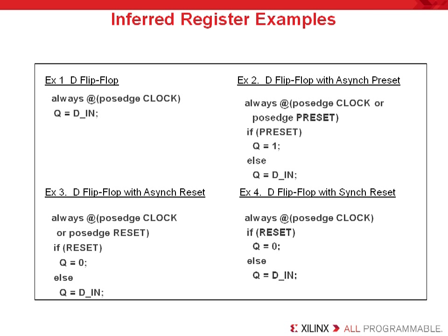As I mentioned a moment ago, using synchronous sets and resets is one of the elements of proper synchronous design. In these examples, you can see that we have inferred D flip-flops with synchronous and asynchronous sets and resets. It is important to remember that for a control signal to be synchronous, it must be contained within the always block and not be listed in the sensitivity list.